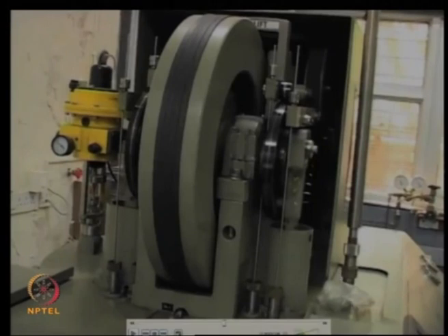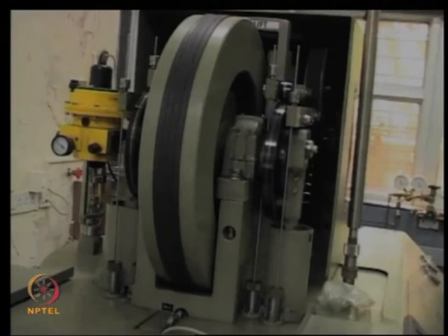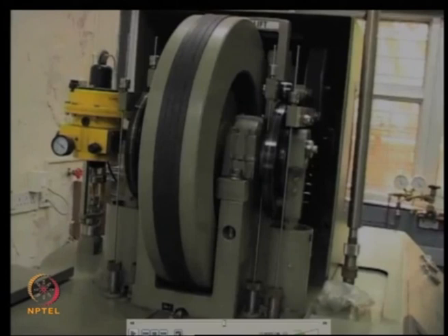And these are the two reciprocating expansion engines, one on this side, one on the other side. As I said, there are always two expansion engines. There could be 4 expansion engines depending on the flow rates, and the flywheel here. Like any IC engine, you have an inlet and outlet valve. So, there are poppet type valves you can see here on either side. There is the inlet valve to the gas, the outlet valve to the gas,